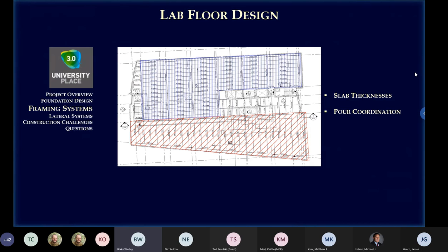from general laboratories to high magnification microscopes, so there's starting to be a lot of variables. Separate variables include what walking speed we would consider that excites the slab, whether it was slow walking, normal walking, or fast walking in a corridor. There's a number of variables that we wanted the owner's team to be aware of